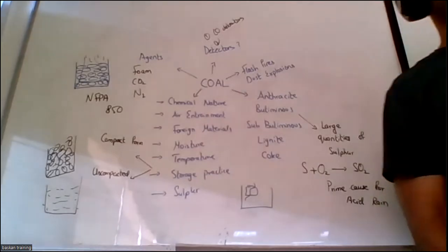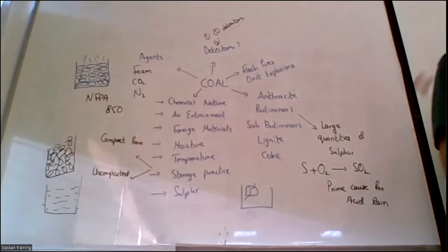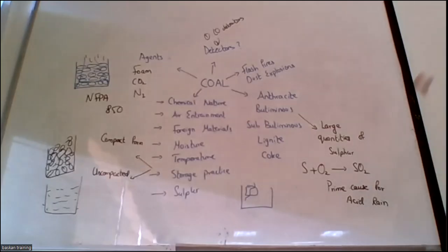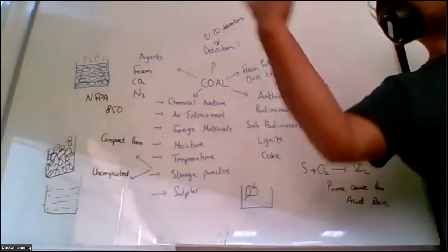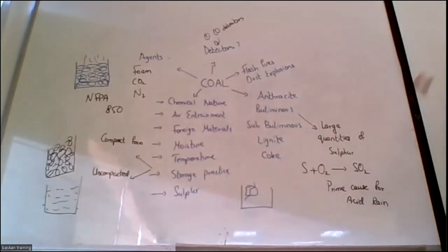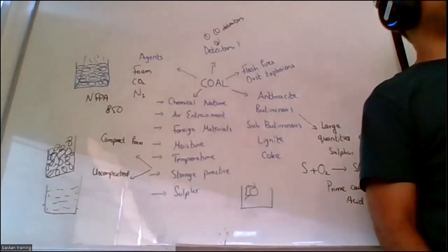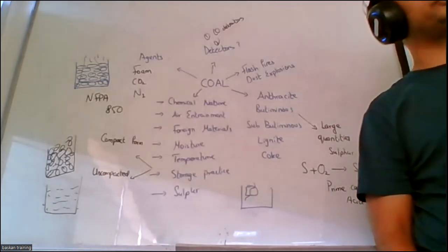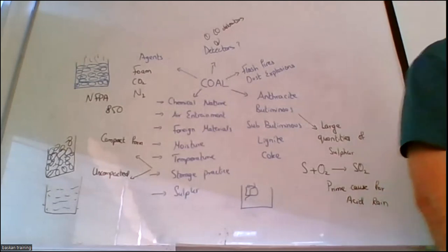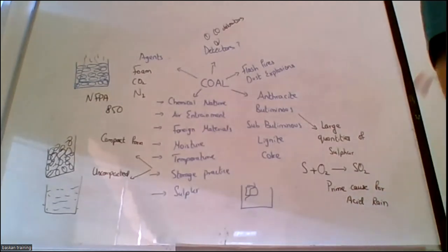Smoke detectors, no. Smoke detectors will always give a false alarm, because we have discussed that whenever the coal is short, dust is released. And where will the dust go? It will always go towards the ceiling. Even in a wood cutting area, we don't use smoke detectors. Wood dust is going to falsely activate it. Dust anywhere is going to falsely activate smoke detectors, right? So that's why we don't use them.